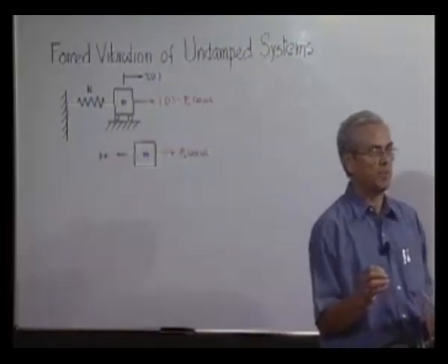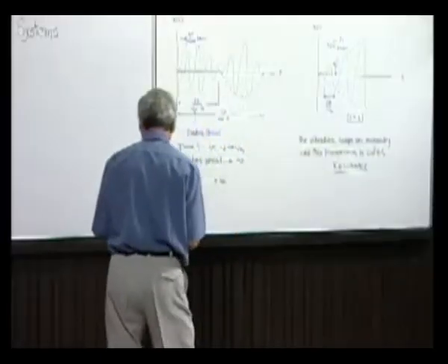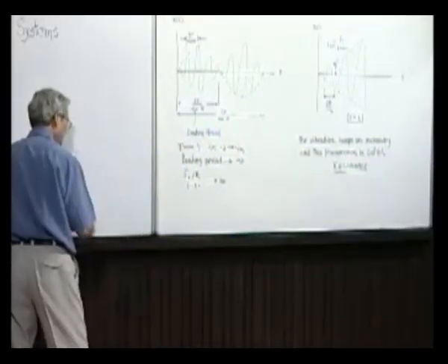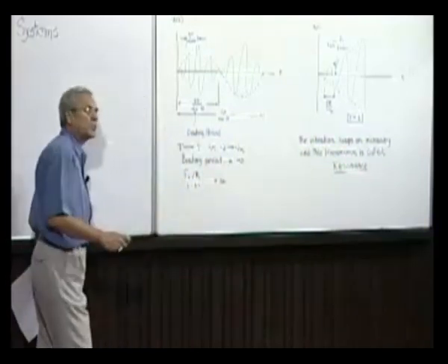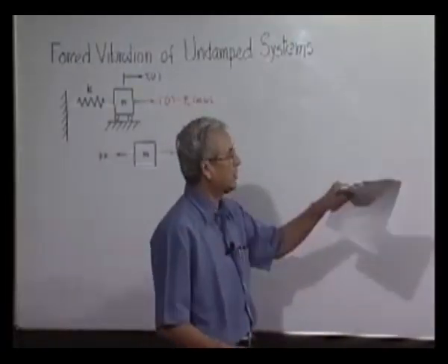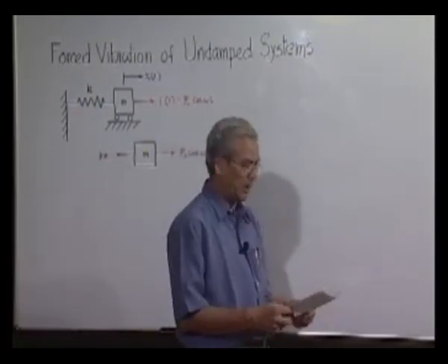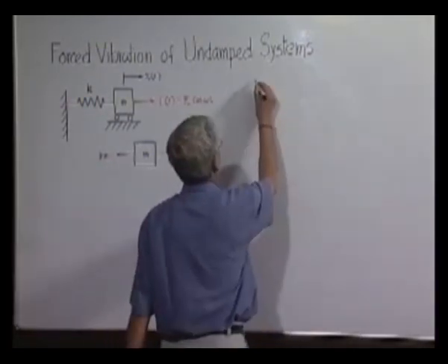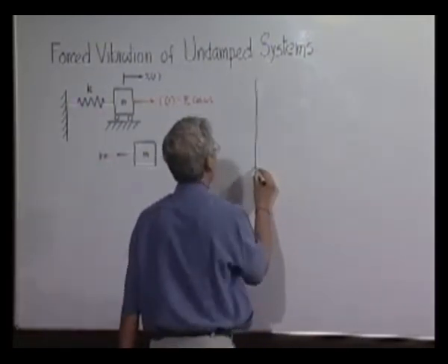It may be very small. And so in reality what happens is that even the very minute amount of damping present in a system will damp out the complementary function, or the free vibration part. And the response will look like this.